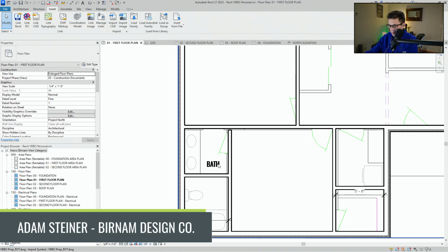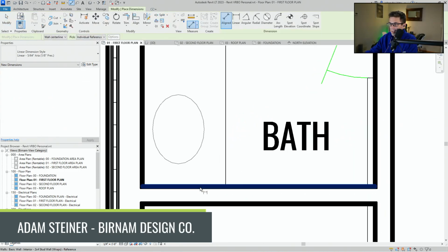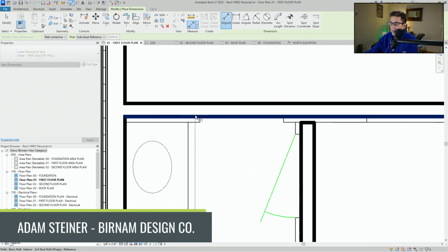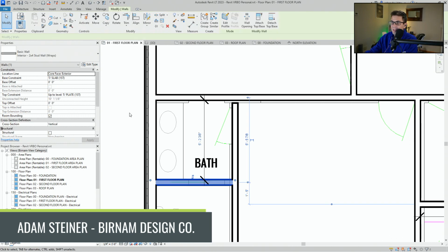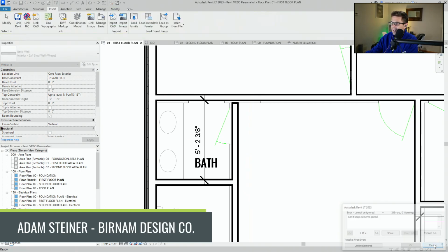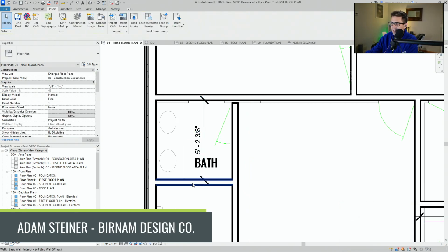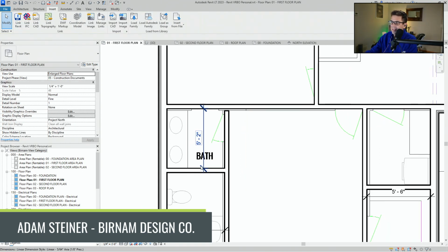All right, just using some dimensions here to make sure these are the right spacing. Oh, this is an interesting one. So the width of the vanity, I actually hear from one of my builders that 62 inches is optimal. Oh, 62 inches, not 62 feet. Every time with Revit. 62 inches is optimal because then they can buy a 5-foot vanity and do fillers, and it's cheaper to do fillers than to adjust the vanity top.